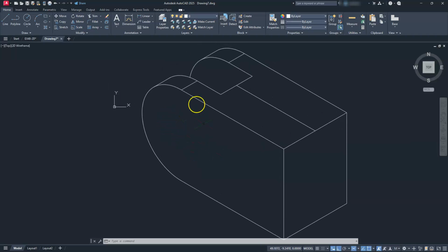We're going to go ahead and put the isocircle that is showing here. So I'm going to switch back to an isometric left. Type in EL, enter, I, enter. Go find the center here. Type in the diameter, right? So we want to use a diameter, so I'll type D, enter, and then the diameter is 20.